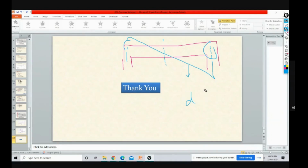Yes, sir. It does not depend only on the shear force diagram, it also depends on the depth. Let's say suppose we require the maximum depth; now here we have provided only 120 overall depth. So if you go for 300 depth, then definitely we have to provide the shear reinforcement for the slab. Practically it is not possible, because we reduce the span and then we reduce the depth. Another parameter we are using.